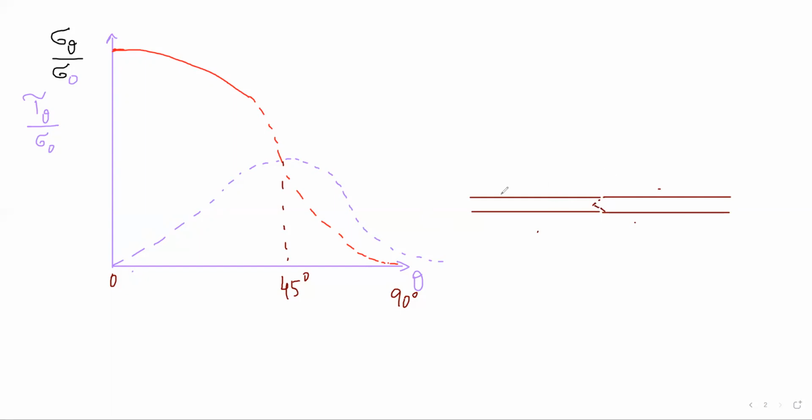It does make sense because I see that at 45-degree angle, not only normal stress exists, I also have a shear stress that exists. But when I look at this plane, I have a huge normal stress that exists. So you keep taking a knife and keep on cutting sections like these. Normal stress keeps on existing, but shear stress does not exist. But at a 45-degree angle, yes, it is true that the normal stress, the red line, is way less than it could have existed when you have a surface like this, but you also have shear stress.